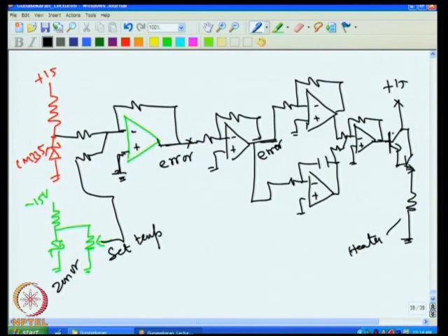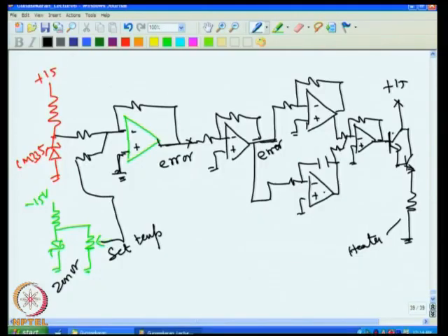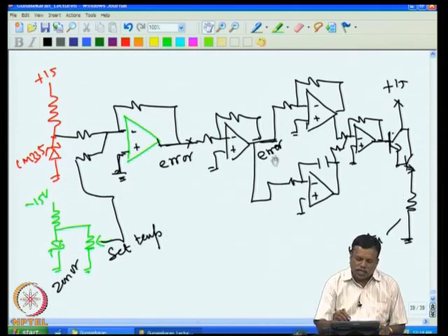Now we have to see this carefully from another angle, how this removes the error voltage. Because once you put in this integral stage, eventually you will find that if you set 80 degree, the temperature also stabilizes at exactly 80 degree, there is no error at all.